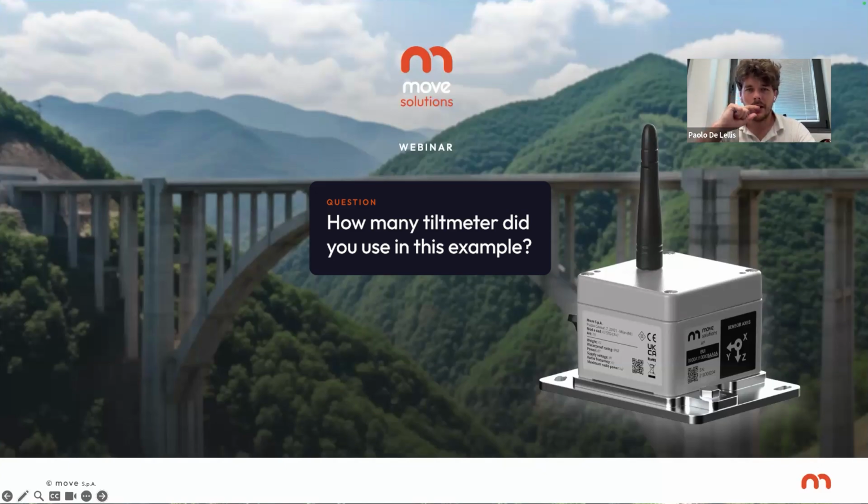Okay, I think that we answered also the other question to understand how many sensors we need for the tools. So in general, for the static deflection, minimum 4 sensors. For the tiltmeter chain tool, the minimum is one, but of course you discretize the length with one sensor.